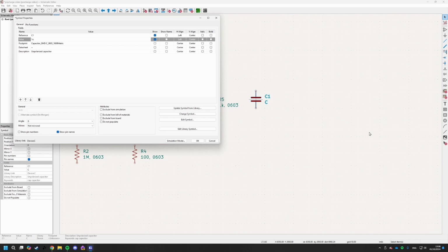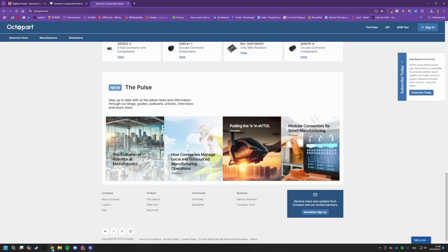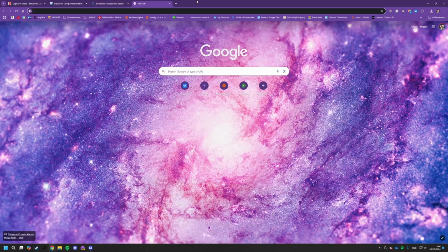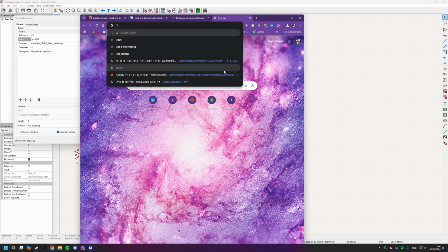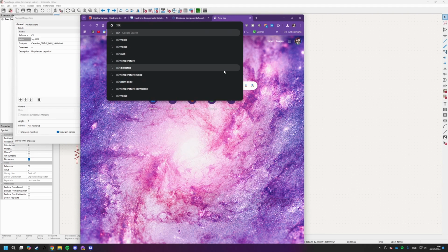There's also an additional consideration with capacitors because they have a voltage rating and a noise rating, noise slash voltage response. So there are two ratings that would fit our purpose, which are X5R and X7R.